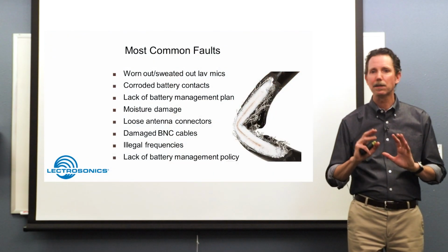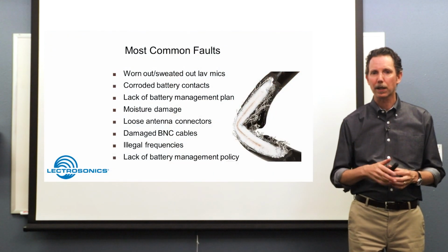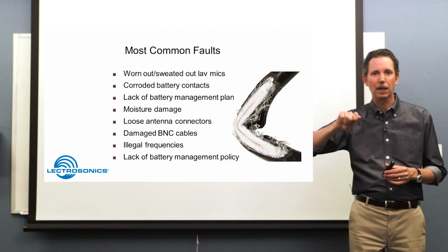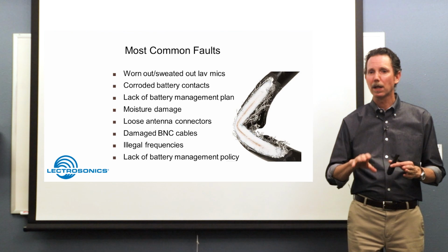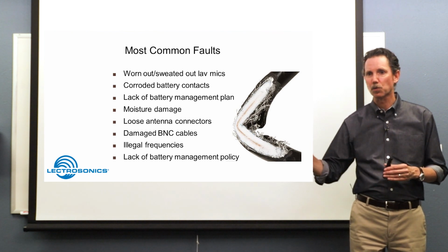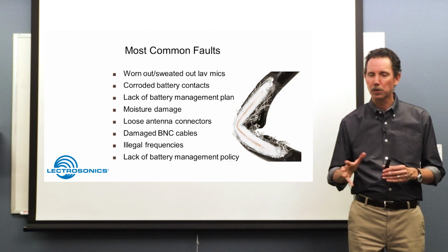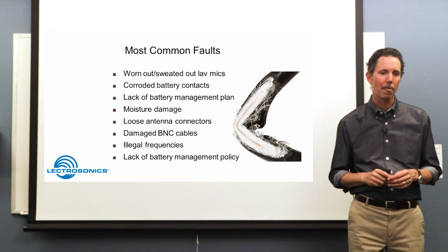Loose antenna connectors, can't tell you how many times I've run into that where I check through a system and some of those antenna connectors become loose over time, especially if you're doing anything where you're moving equipment around. Even if it's just rolling it down the hall, those vibrations can loosen up those connectors, so check those.